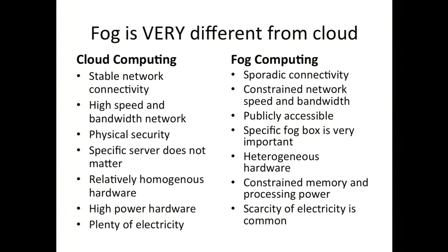So a really good example of this is, how many people have heard of Sigfox? Do you know this company? Okay, a couple. So I love Sigfox, but you're looking at getting about 20 bytes through in a transmission, and it'll take you about 4 seconds to get it up and 15 seconds to get it back down. So if you want to lock the wheel of something that's being stolen, probably not going to cut it, because 15 seconds is enough time for someone to just roll that right into their truck. So self-locking bicycles should probably have some edge processing going on.